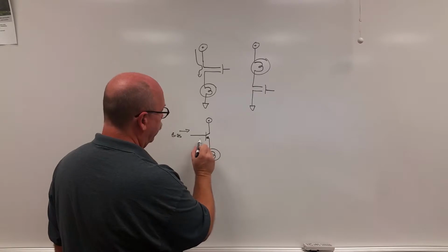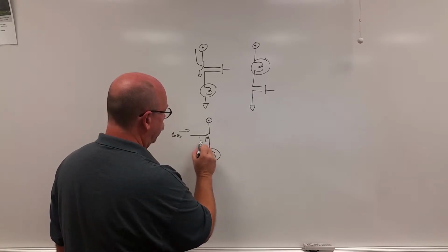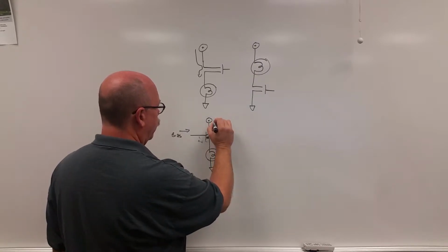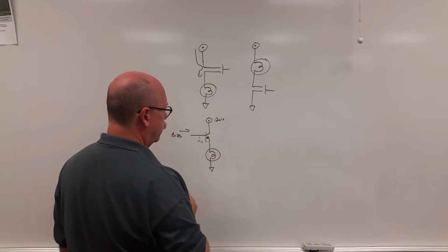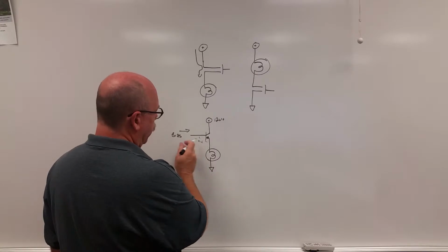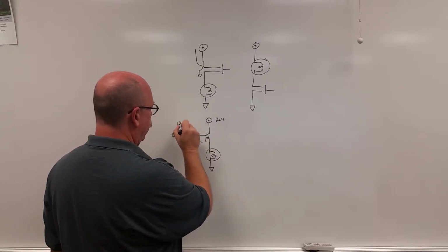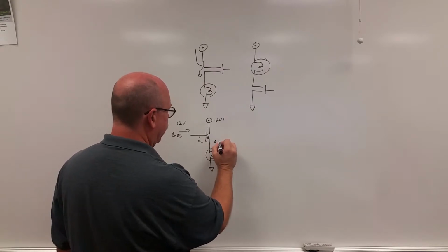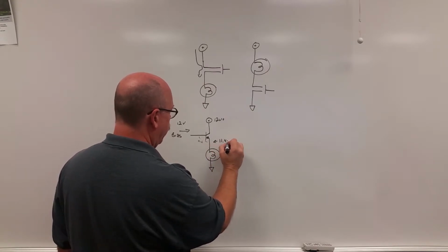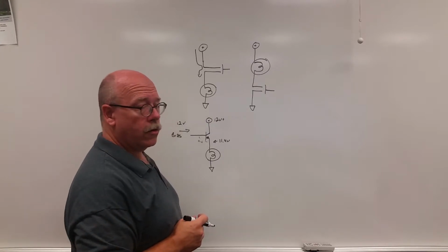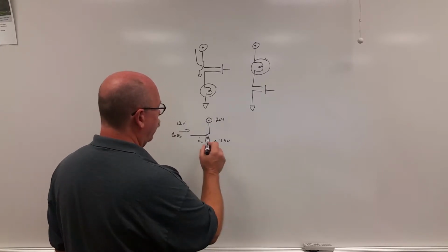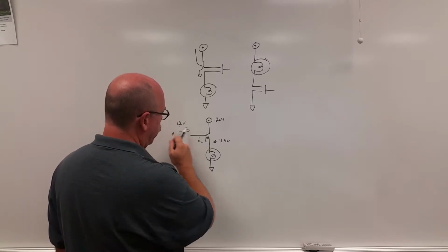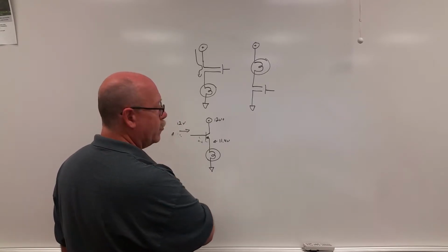And remember, it takes 0.6 of a volt between these 2 points to turn it on. So let's say this is 12 volts. If I put 12 volts into this, I would have out here about 11.4 volts. So it would turn the light on. However, we're limited because we have 12 volts here, and this is all the voltage we have available.